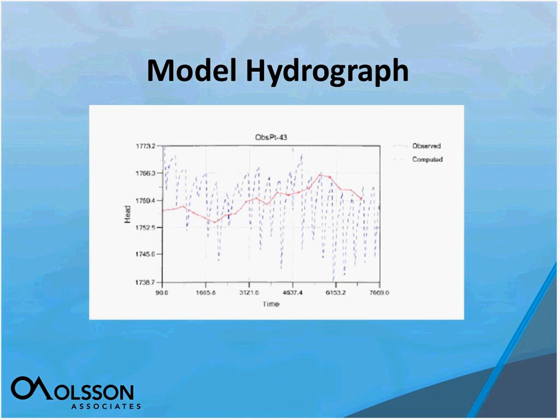Then what we do is we take the information that was gathered from the water level measurement points from the NRD, and we put that information into our groundwater model. And so that's what we call, in this diagram, the observed water level measurements. And as I said before, these are the water level measurements taken once a year in the spring over the 20-year period.